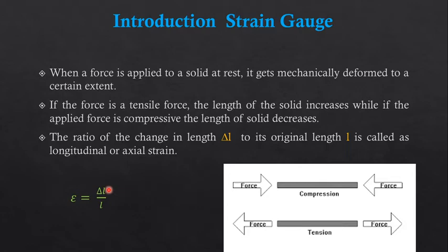We know that the atoms in a solid are bound together by interatomic force. If no force acts on the solid, the atoms maintain a definite distance among themselves at a given temperature. In equilibrium, this distance is called the interatomic distance or bond length. The bond length increases or decreases when a force is applied to the solid. Because of the interatomic force between the bonds, a force of restitution acts to restore the atoms. That's why the energy required by the material, or by the rod in this example, depends upon the interatomic force of that particular material.